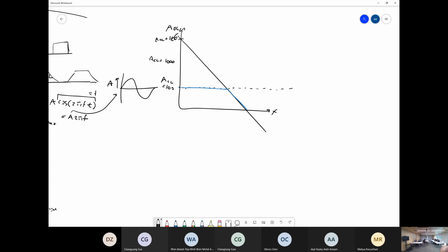Again, this is just a cartoon, so it's not totally accurate. It would look like that. So you can see the bandwidth effectively. My 3 dB point of something with higher gain has less bandwidth, and something that has lower gain has more bandwidth, right? So that's roughly how you approximate the gain bandwidth product.